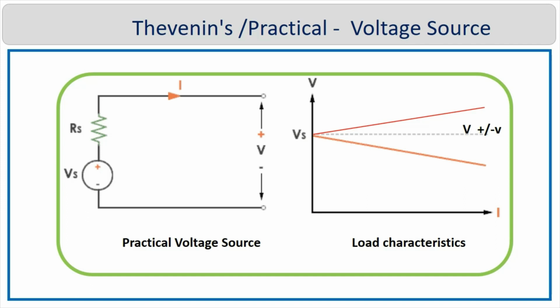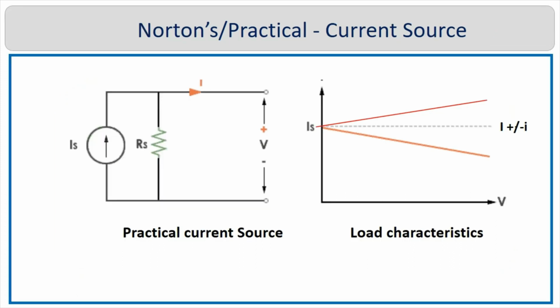An electrochemical cell is a popular source of DC voltage, and alternatively DC can also be derived from AC mains supply. A practical voltage source as defined by Thevenin's theorem is made up of an ideal voltage source connected in series with its internal impedance, which limits the load current and also leads to a voltage regulation issue. A voltage source connected in series with a transistorized common base regulator increases the internal impedance and creates a constant current source. A practical current source as defined by Norton's theorem uses an ideal current source connected in parallel with its output internal admittance, which limits the maximum load voltage and also leads to a current regulation issue.